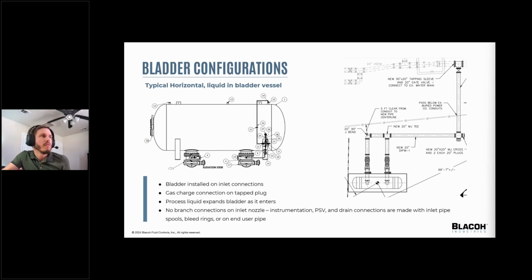So if you do know the volume you need and you're trying to figure out your diameter and length pair, there are usually dimensional constraints, especially if the vessel is going into a vault or a pump house or some kind of building. So those can sometimes drive your choice.